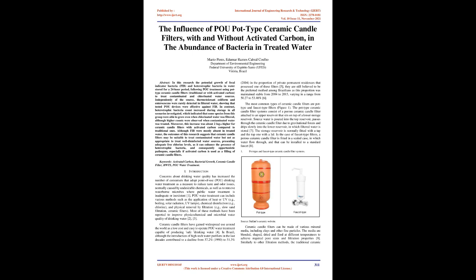Although FIB were mostly absent in treated water, the outcomes of this research suggest that ceramic candle filters may be suitable to treat contaminated water but not as appropriate to treat well-disinfected water sources, presenting adequate free chlorine levels, as it can enhance the presence of heterotrophic bacteria, and consequently opportunistic pathogens, especially if activated carbon is used as a filling of ceramic candle filters. Keywords: activated carbon, bacterial growth, ceramic candle filter, HWTS, POU water treatment.